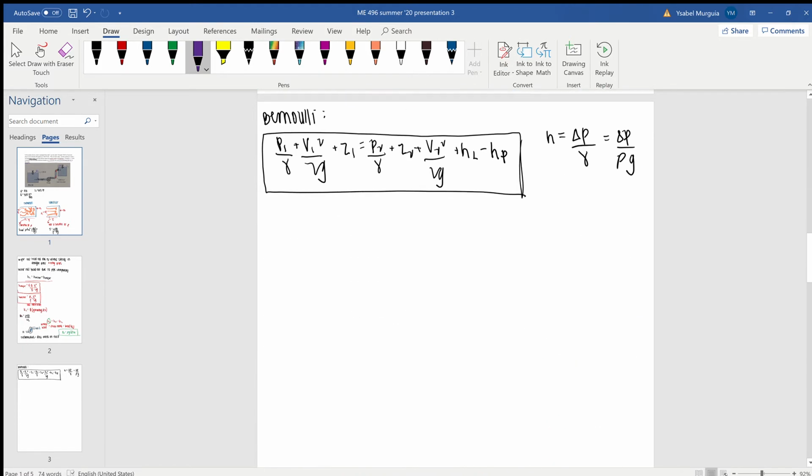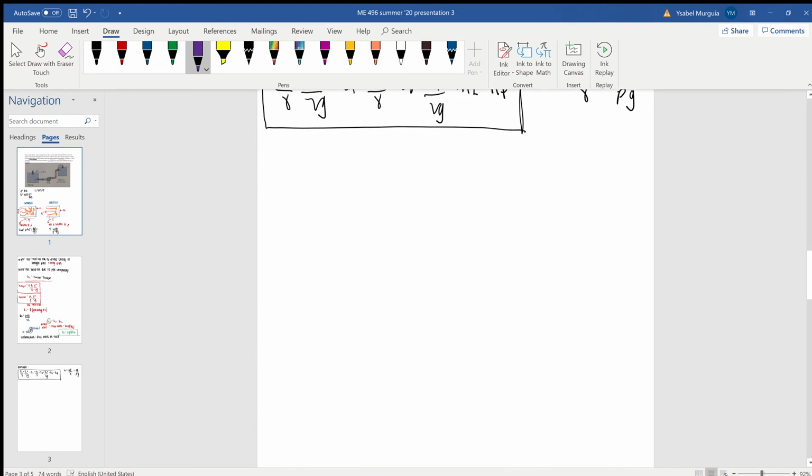I am going to define some constants for use throughout this problem solving. These are just pulled from the book, but I want to list them. The roughness of cast iron, from a table in the textbook, is 8.5 times 10 to the negative 4 feet. Rho is equal to 1.94 slugs per foot cubed.